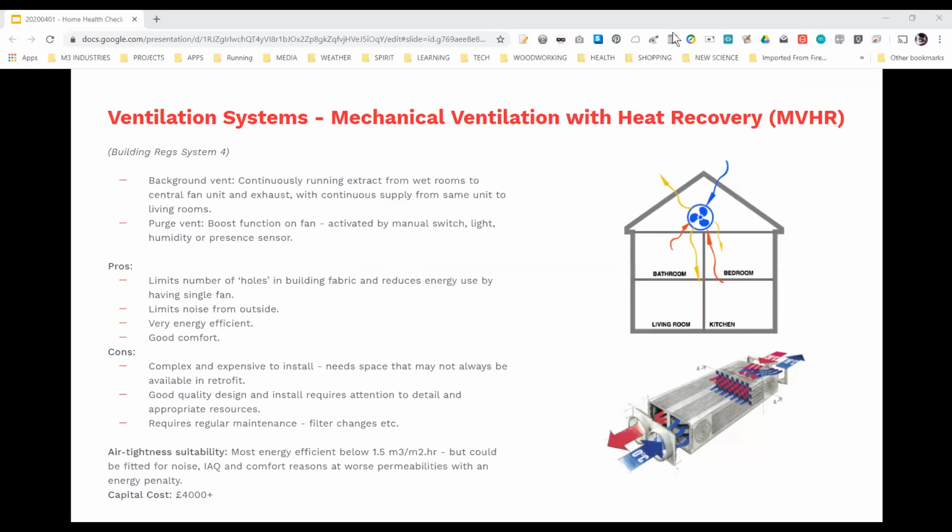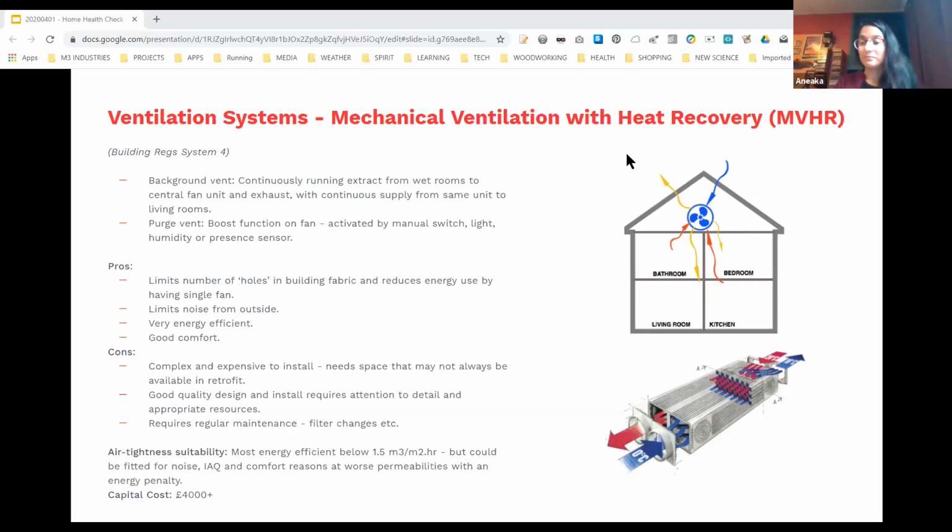Sorry, if I could just jump in on the UPVC double glazing. Yes, you can fit trickle vents into double glazed units. Last time I checked, Screwfix actually sell them. But they are fiddly to fit. You should probably go to a window installer to have them done. Sorry, I'll go back on mute now.